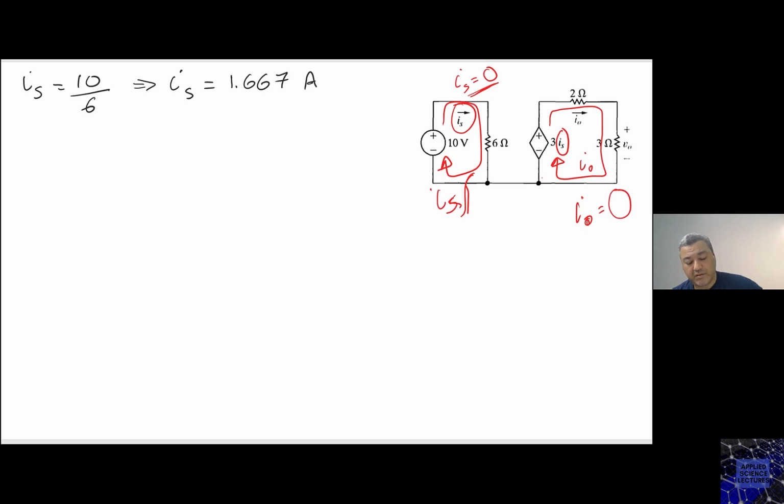Because you basically created an open circuit then. Because IS is 0, the potential difference now across this dependent source is 0. That's the link between those two circuits. So physically they are separate and sharing this potential, but they're still bound by the controlling variable. Does this make sense? I think so, yeah. Okay.